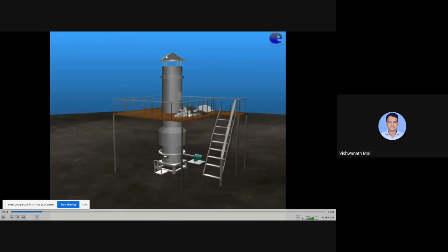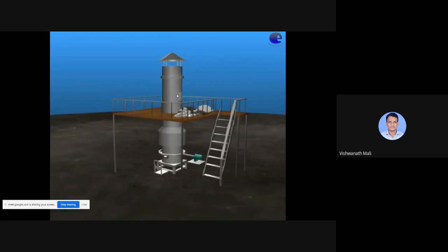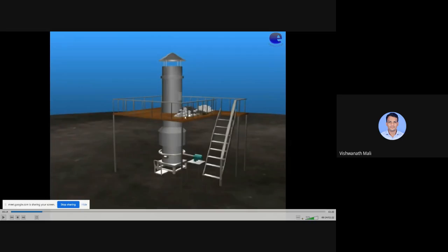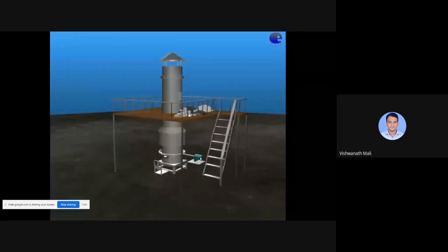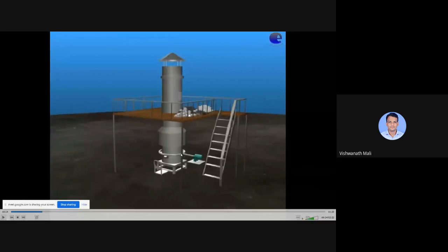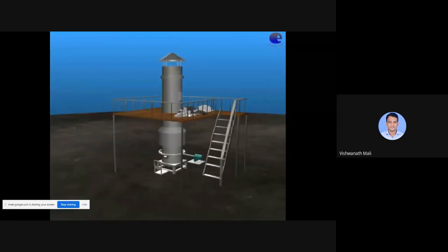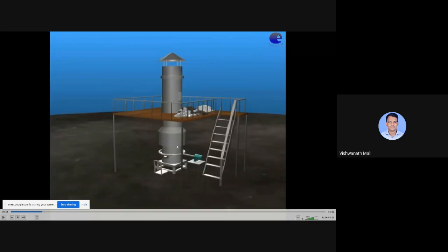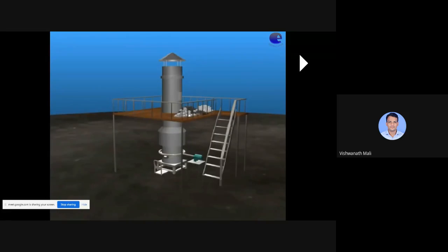Here you can see. Then there is a floor, from which we charge this furnace. So these are the charging materials like pig iron. Okay? And here you can see the machine blower from which we pass the air so that we can get more flame of this fuel. Right. Now we will see the inside part.